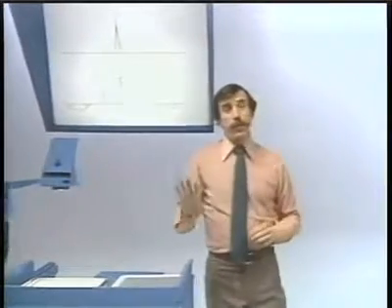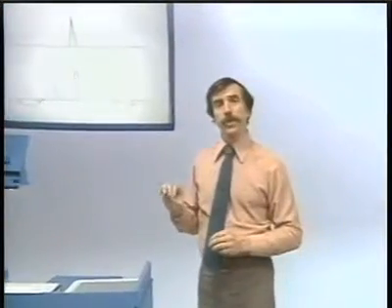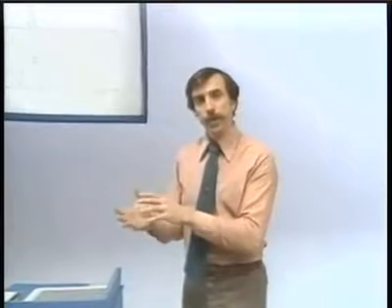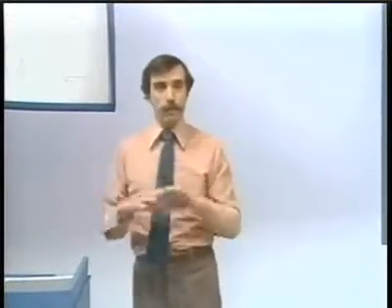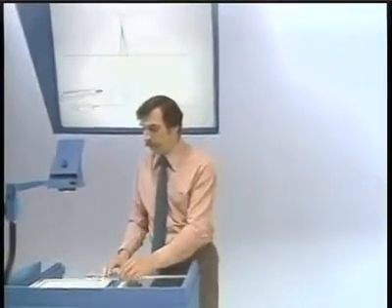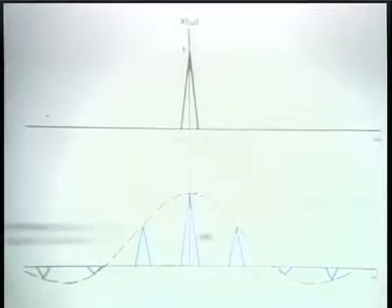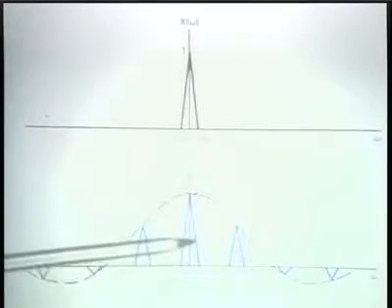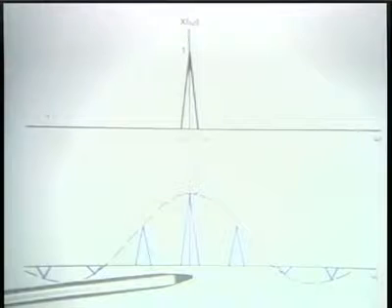Now, there's a very important thing to observe here, which is that the ability to do the reconstruction is associated with the notion of whether we can extract that kind of central triangle. I happen to choose a triangular shape, but obviously I could be talking about any shape as long as it's band limited. Notice that in this modulated output spectrum, the ability to recover this is totally independent of what the value of delta is.